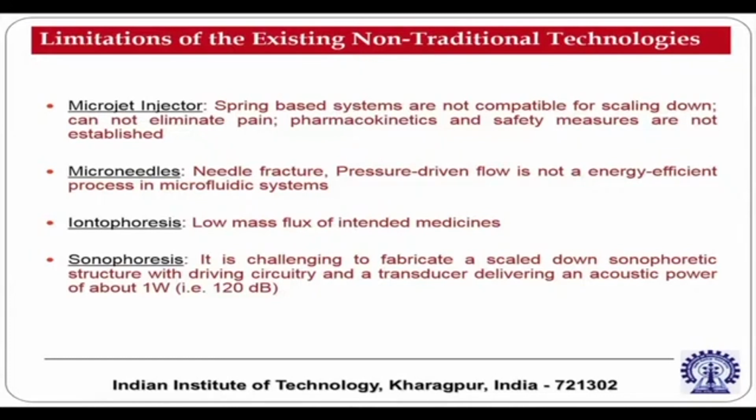In iontophoresis there is low mass flux of intended medicines, and in sonophoresis it is challenging to fabricate a scaled down sonophoretic structure with a driving circuitry and a transducer delivering an acoustic power of about 1 watt, that is 120 decibel.